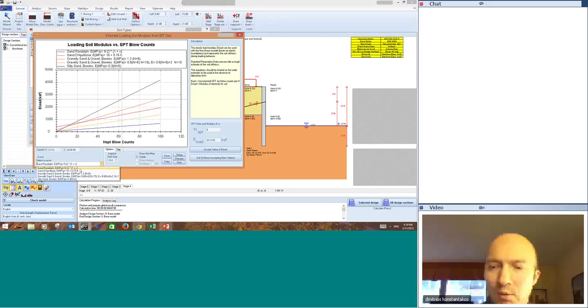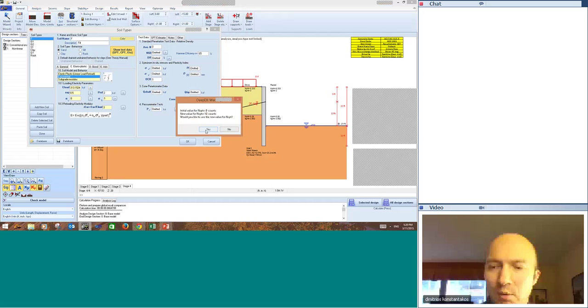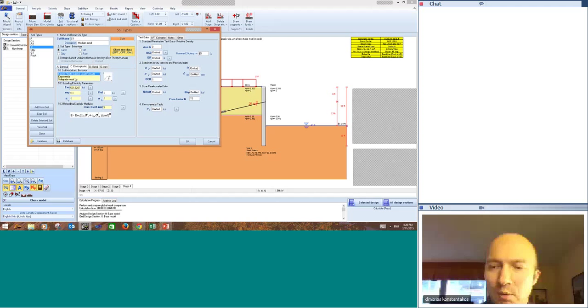We can choose the soil type that better describes our situation. We can go in with an SPT of 10. It comes back with 532. I will probably round this up to 500. We never know the modulus of elasticity that well. We can go on soil type S1. Let's say that this is a stiffer soil.